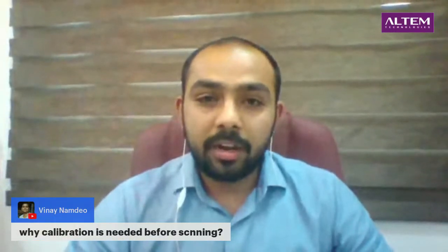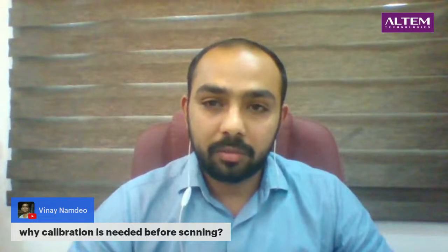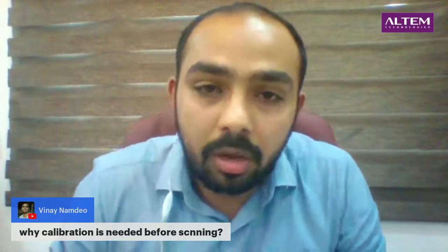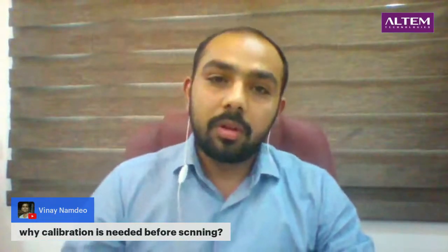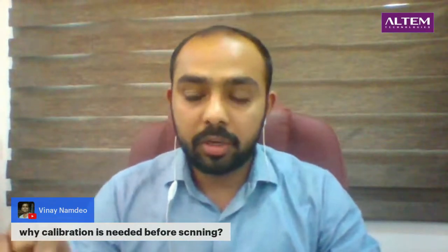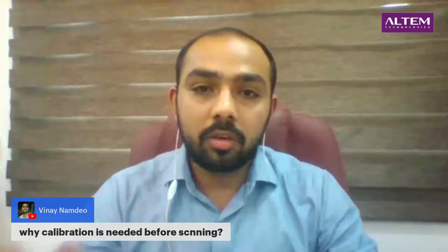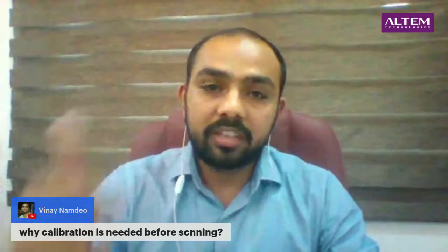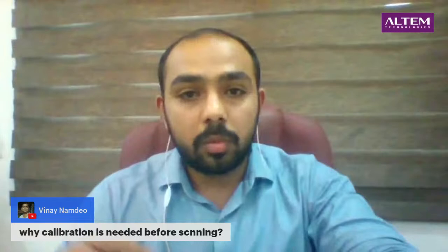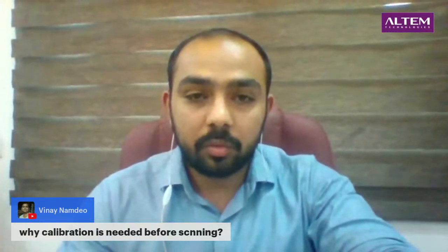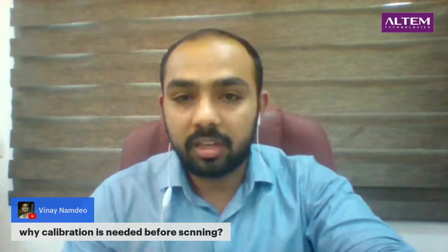If any distortion happens under that condition, we will look at calibration; otherwise, no calibration is needed. You also need not place any target marker for reference, because our scanner works on live tracking of the texture as well. The texture is marked as the reference, and that is the major advantage. That's why we need not require any target marker, or any spray over the parts.